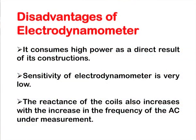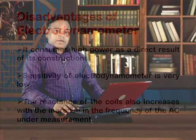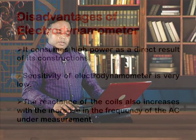Now, considering the disadvantages of the electrodynamometer, we say that it consumes a high amount of power, which is the direct result of its construction. The power consumption is higher because the same current which is to be measured is itself producing the magnetic field. So, the magnetic field should be strong enough to produce a deflection. So, we say that the electrodynamometer consumes higher power.